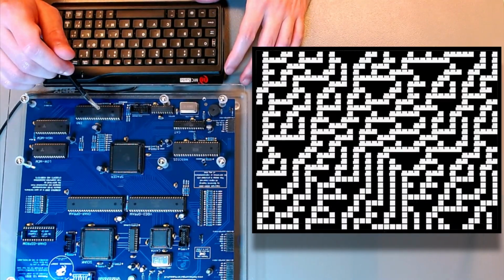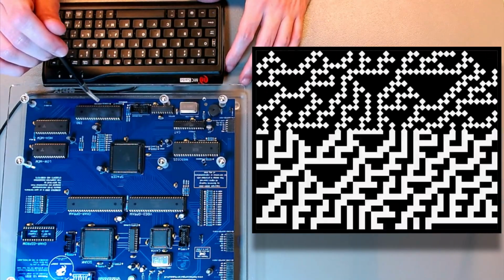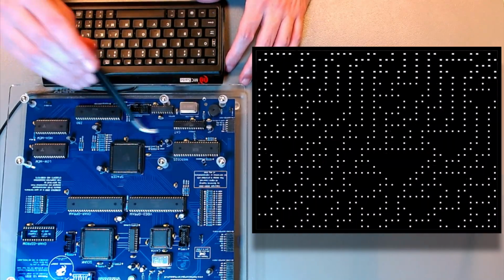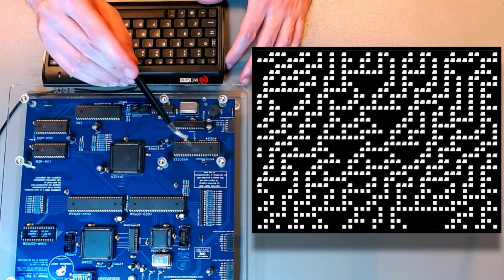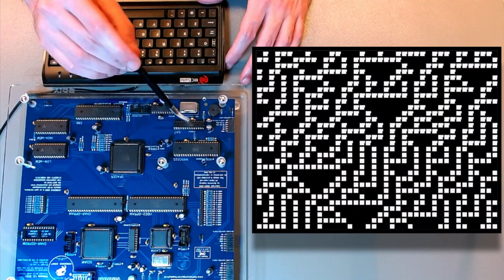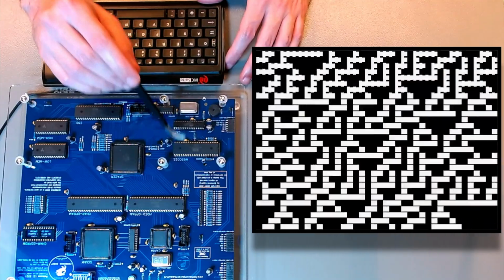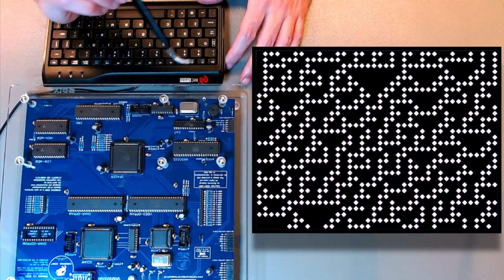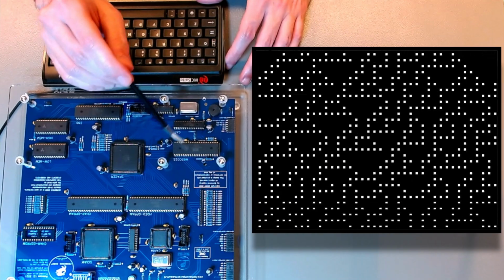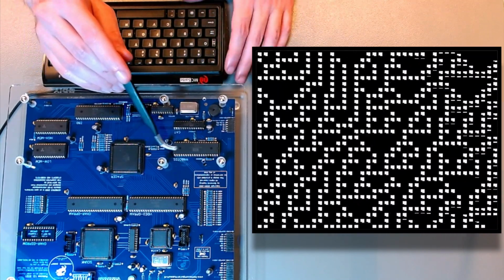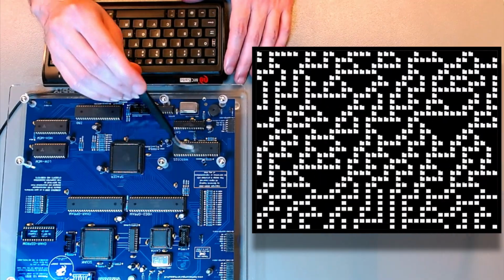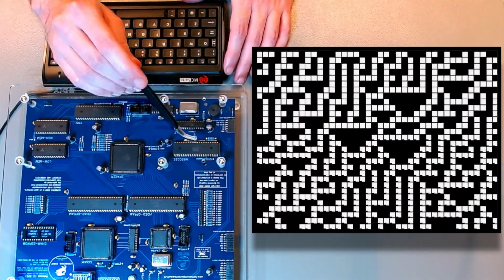So the Z80 is naturally faster for this kind of software scrolling application anyway, but in this case the 6502 has the additional handicap that a lot of the timing required for this transfer of control protocol is done in the CPLD. And you might ask, well, if I don't press S and let the thing run by itself, no transfer of control is happening. Yeah, but there is still something else.